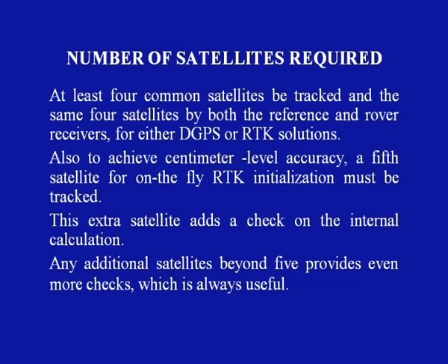Also, to achieve centimeter level accuracy, a 5th satellite on the fly RTK initialization must be tracked. This extra satellite adds a check on the internal computations. Any additional satellite beyond 5 adds even more checks, which is always useful.